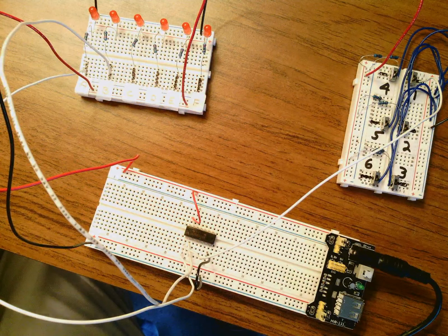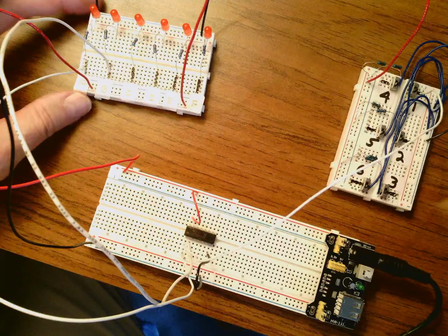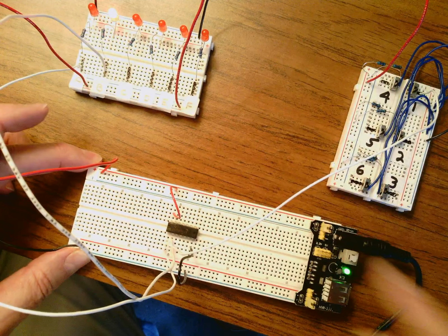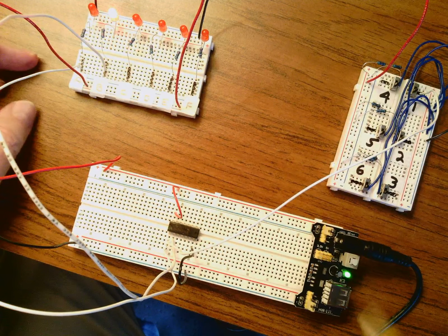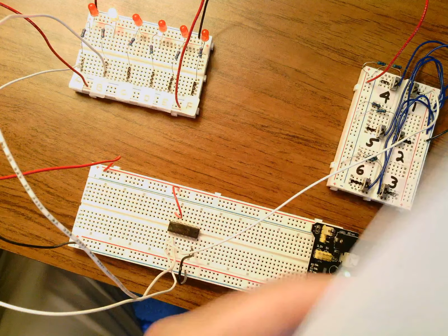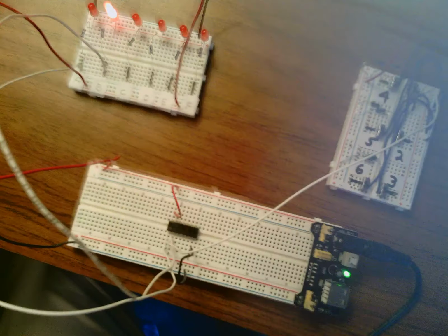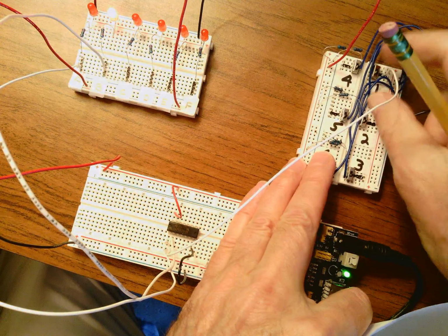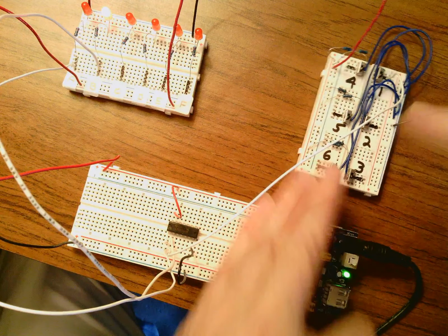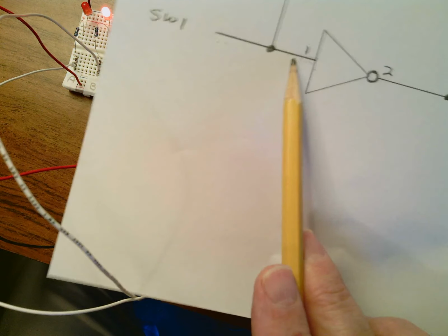Now, let's see how this circuit works. I'm going to turn it on by pushing the main circuit board. I want you to notice something. I just turned this circuit on, and switch 1 is low. I have this slide switch up here, and switch number 1, I have it down. So that puts a 0 on the input. So I have a 0 here, which keeps LEDA off. And a 0, the inverter makes it a 1 out here, which is +5 volts, which just turns LEDB on.